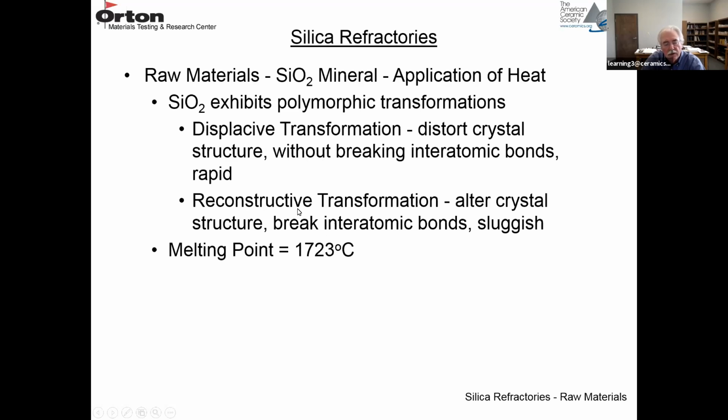And then there's another one, reconstructive transformation. Here you alter the crystal structure. You're actually breaking bonds and forming a new crystal structure. And that's a very slow or sluggish reaction.